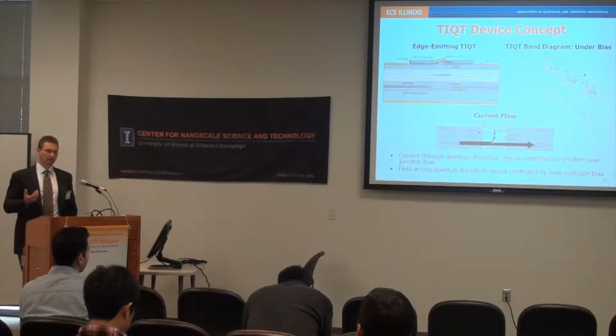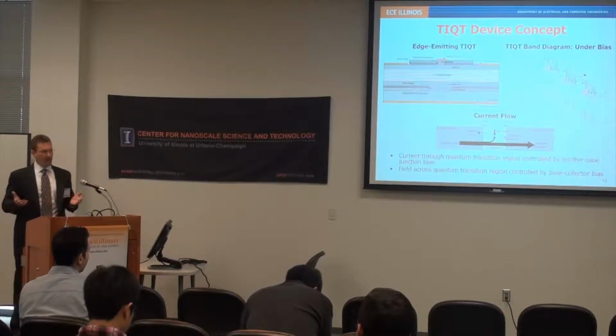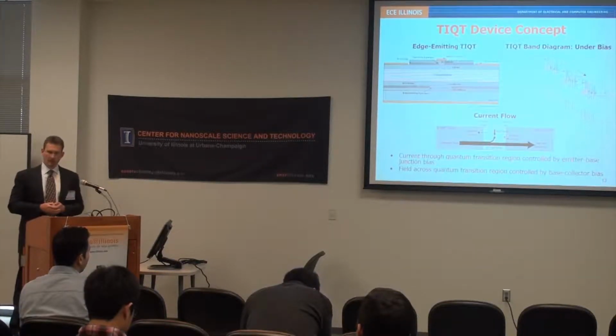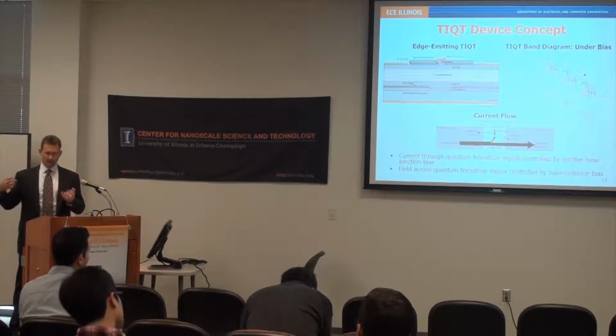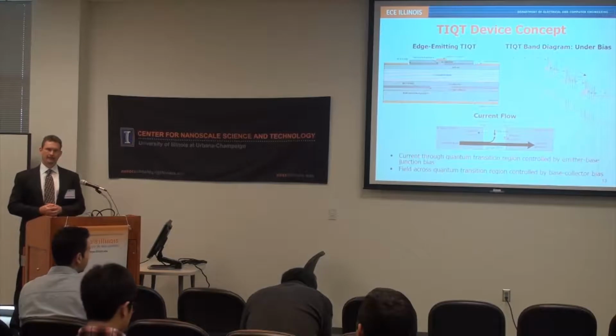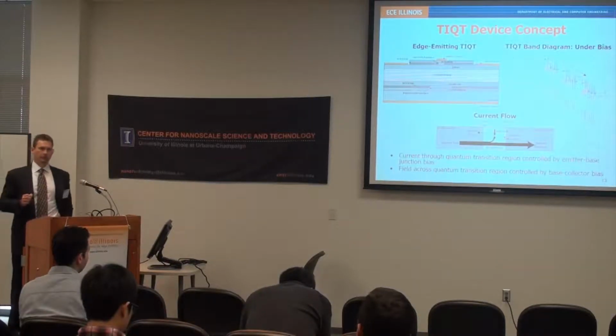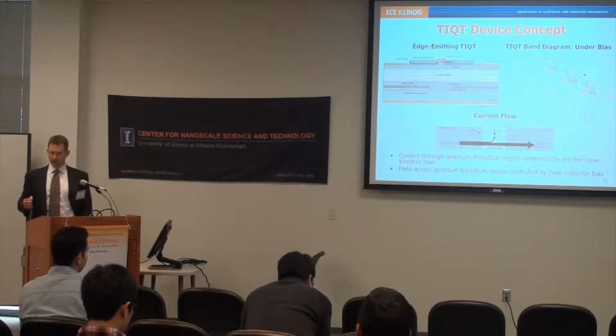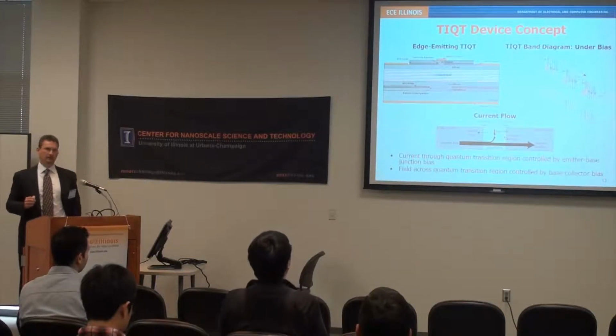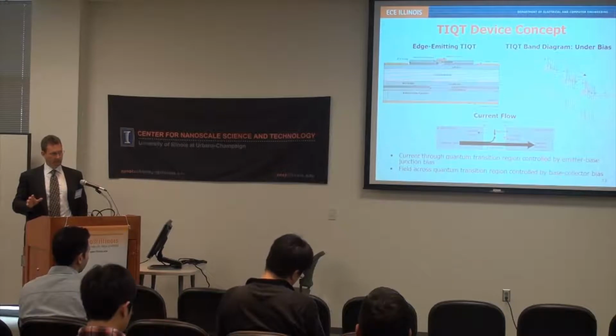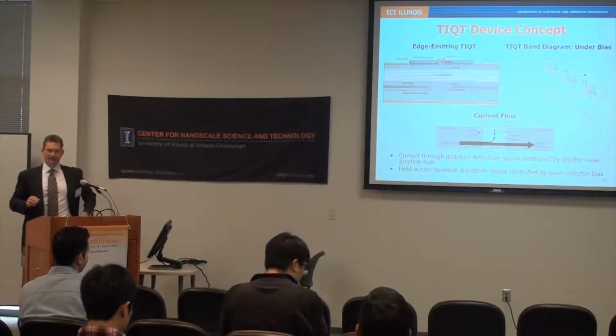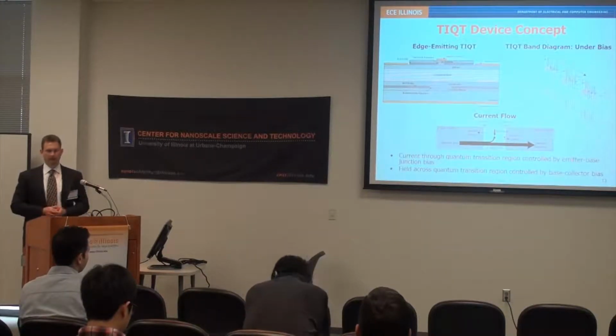So effectively what we do is, we have a transistor or an HBT. We have a standard base junction, we have a collector junction, we have an intrinsic region that contains our quantum cascade structure. We apply a reverse bias to that structure, which applies the field, and we engineer the doping in both the base region and the collector region to create a depletion region around that quantum cascade region, which strips out the carriers that are contributing to free carrier absorption.